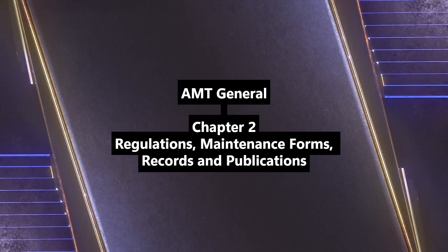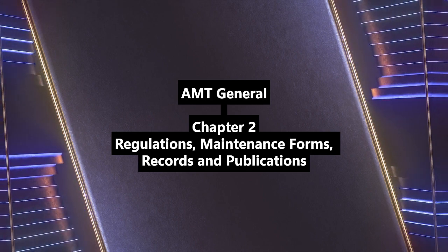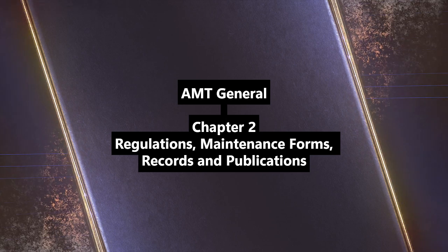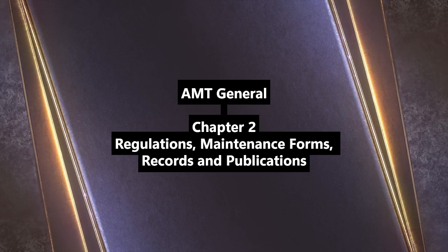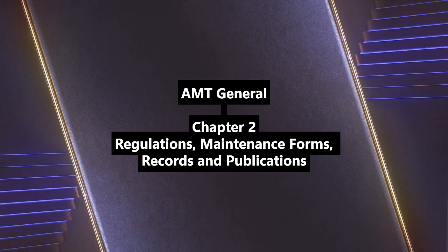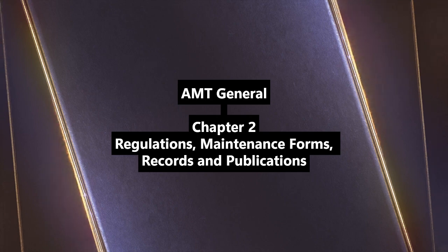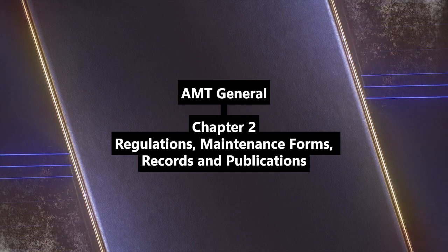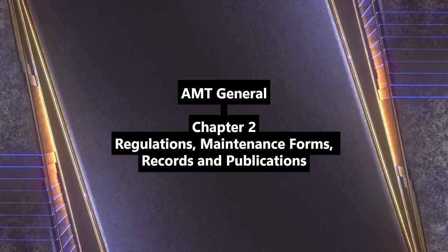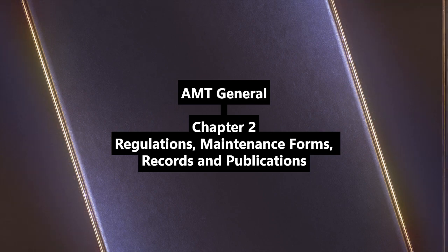What about Special Airworthiness Information Bulletins, SAIBs? These are informational alerts, education, recommendations, non-regulatory, used when something doesn't meet the criteria for an AD but warrants attention. Like the Cessna seatbelt bracket example, recommendation, not mandate. Exactly. SAIB CE-15-13 referenced a Cessna service bulletin recommending steel brackets instead of aluminum, but it wasn't an AD at the time.